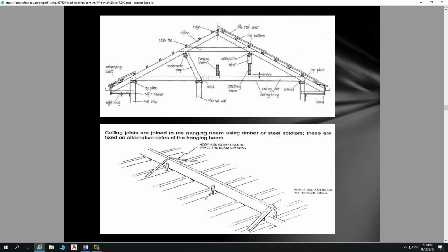If we were to go a raked eave, so we remove this soffit bearer, this piece of timber out of here, and we just have this rafter carrying down, and our soffit lining, or the eaves lining, follows the underside of that rafter, then we would have to consider the span, or the cantilever of that rafter, in determining what size that rafter needs to be. And typically that can be a limiting factor in design as well.